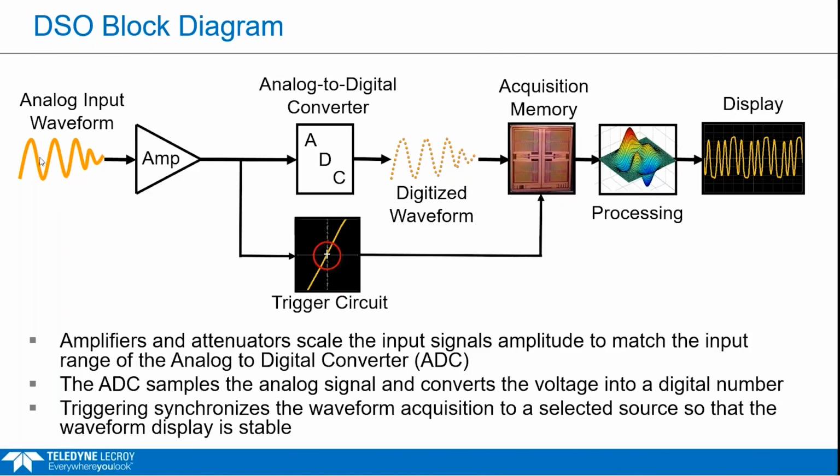Nonetheless, if we have a large signal, we've got to reduce it so the amplifier can take it, and then from there we'll attenuate and amplify as needed to get it in front of the ADC. If we have a small signal, then a divide by 1 or times 1 probe is going to be helpful, and therefore we'll get, again, the right amplitude into the BNC so that the amplifier, the scope, can deal with it. That's how it plays in. It's just getting the right signal level at the start to the BNC of the scope.